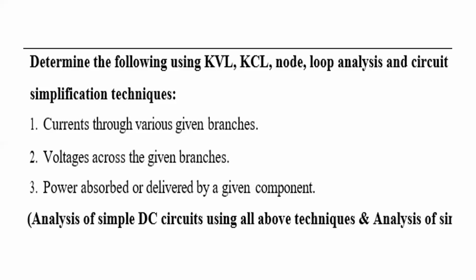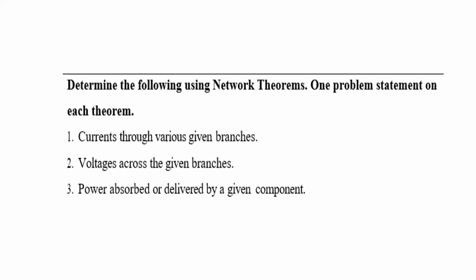And if you want to find power absorbed, then how to calculate power? Power is calculated as I square R. Current value you have already calculated, so you calculate I square R. That will be power absorbed or delivered by that particular component. These you can find out after you find the value of current. So you simulate all these, and then for second practical, it will be determine the following using network theorems.